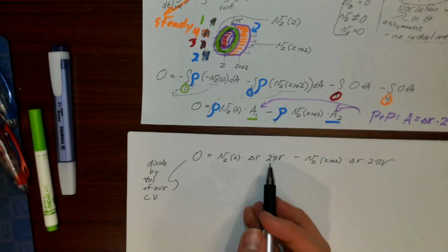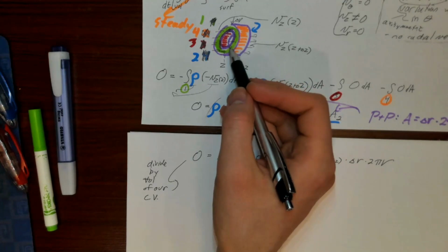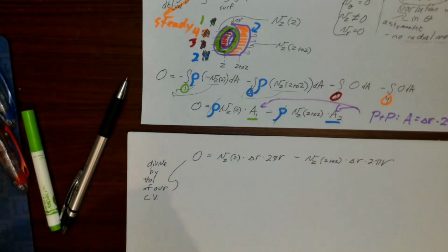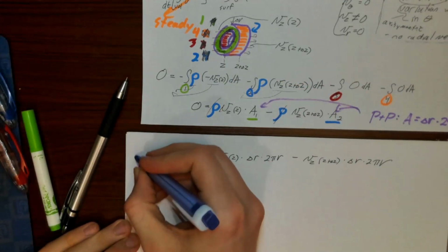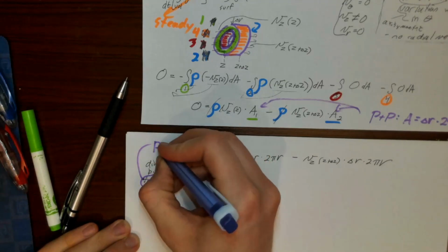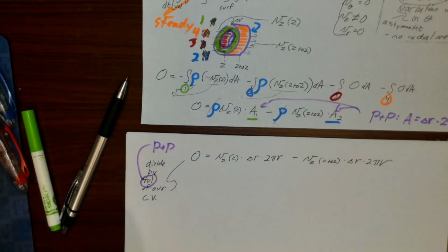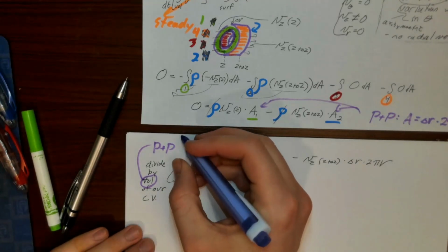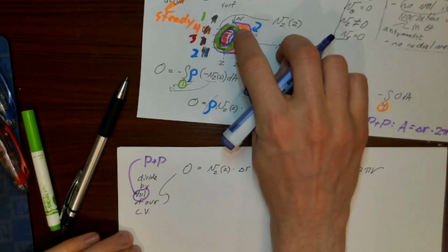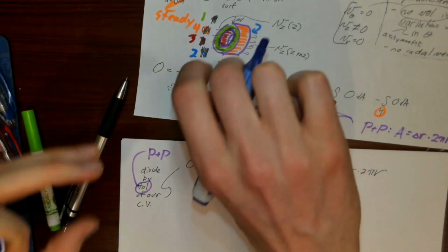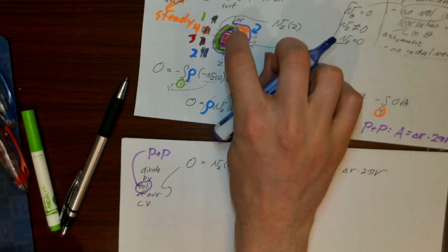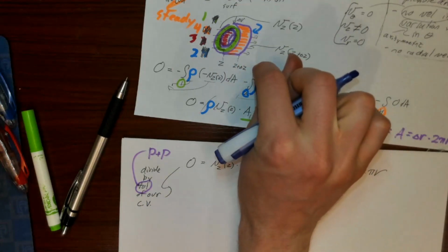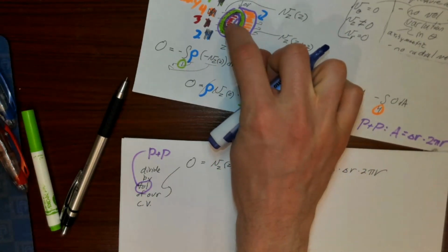So in this case, we'll take a moment now. Pause and ponder: what is the volume of this control volume? Well, hopefully you've done it. The volume of our CV is going to be, if we took this thing that now has some finite thickness and unwrapped it into a rectangular prism, one dimension would be the circumference, 2 pi r.